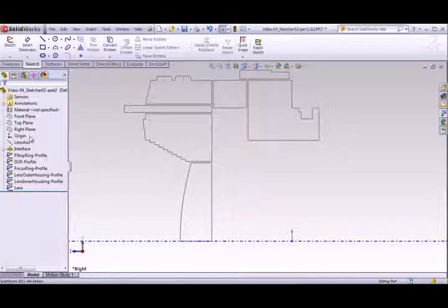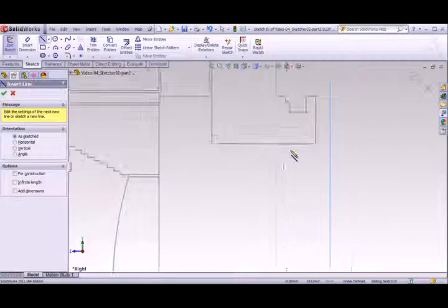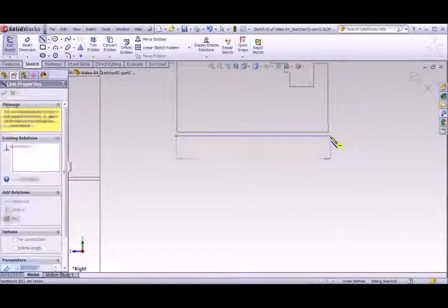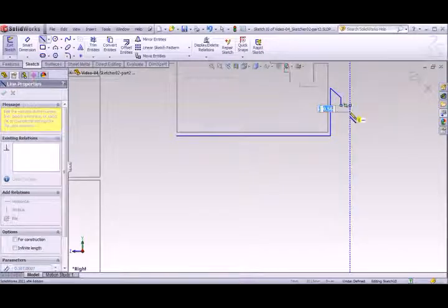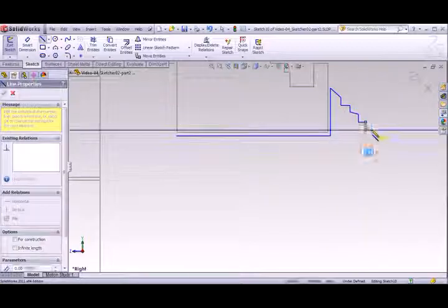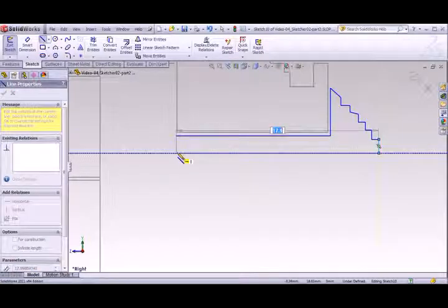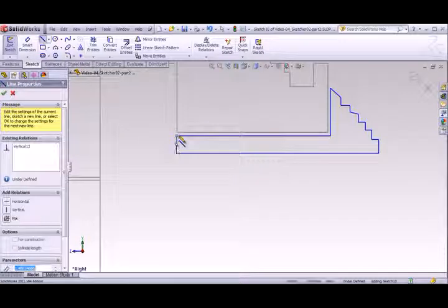Let's select the right plane and then hit the L key on the keyboard to fire off the line tool. Then I'm just going to draw a horizontal line right across here, and then create a diagonal line followed by a horizontal stair step, and we're going to make 5 stair steps. So this will be 1, 2, 3, 4, 5. Then come right down a little bit, all the way back in, like a panhandle, close this guy up.